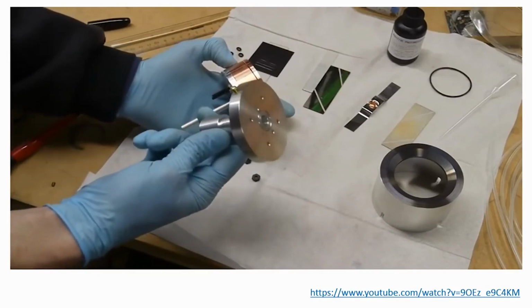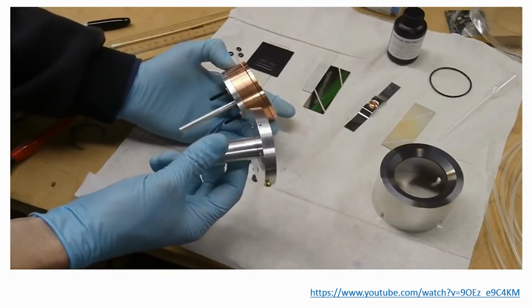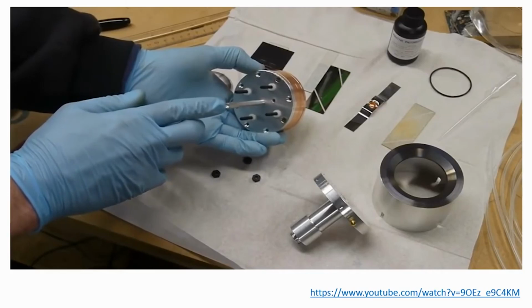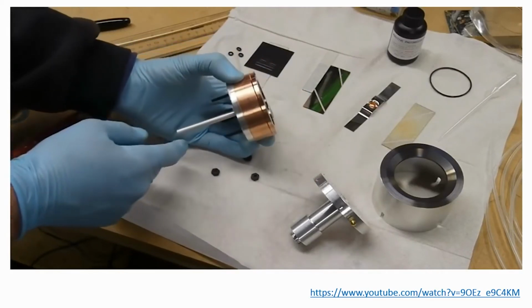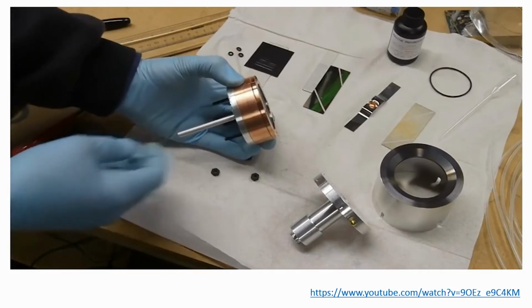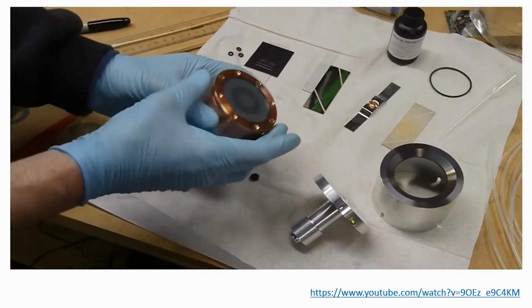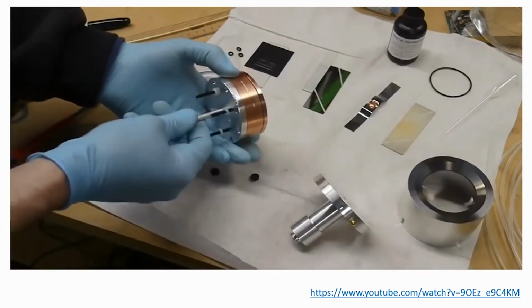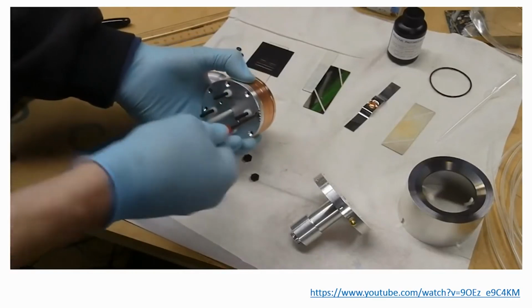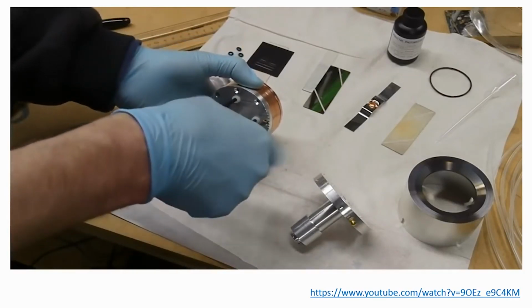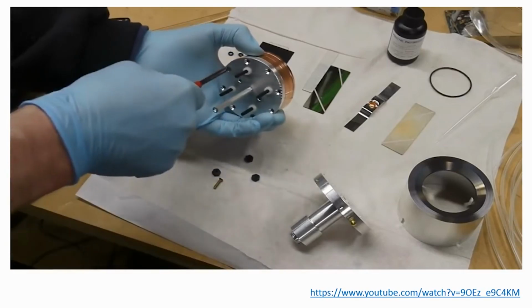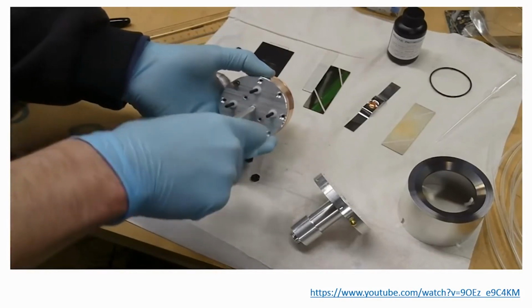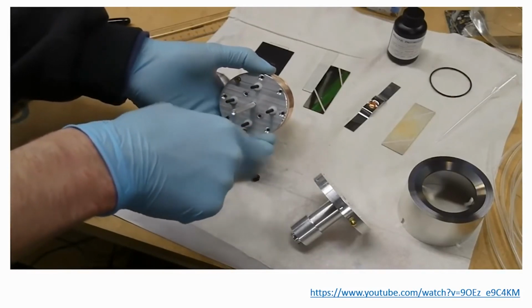And so this part is at the vacuum chamber case potential. Let's just call that ground. And then the inner part here, this is where it touches the spark plug. This is all at a negative high voltage, let's say 1000 volts negative. So inside here, we've got a very high potential between this outer shell and the inner shell, but there's a few other tricks here that allow us to sputter just the target material and not sputter the rest of it. So I'll open this up, and as you can see, I'm missing quite a few screws because I haven't got the right ones in yet, and I just wanted to test this quickly.